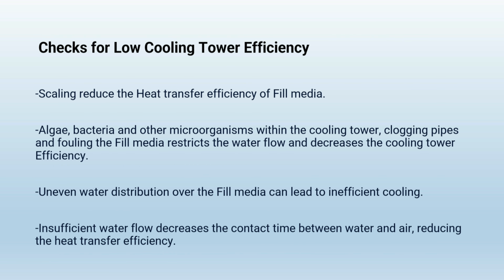Now, my dear friends, what checks are to be done if we have low cooling tower efficiency? First, check scaling, as scaling reduces the heat transfer efficiency of fill media. Then growth of algae, bacteria and other microorganisms within the cooling tower. Fouling the fill media restricts the water flow and decreases the cooling tower efficiency. Also, uneven water distribution over the fill media can lead to inefficient cooling, and also insufficient water flow decreases the contact time between water and air, reducing the heat transfer efficiency.